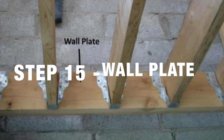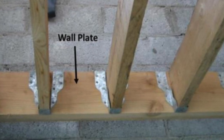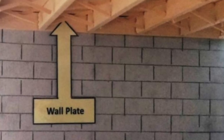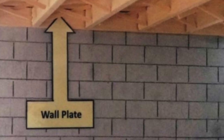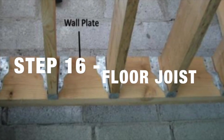Wall plate. The wall plate is a key element to timber upper floor, and similar to suspended timber ground floor, the wall plate's main function is to support the floor joists. And on the working model, we are using basswood strip and we glue it to the internal frame wall.